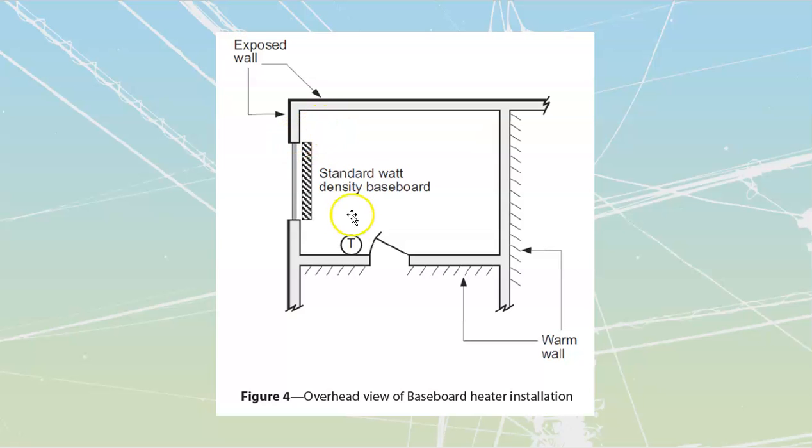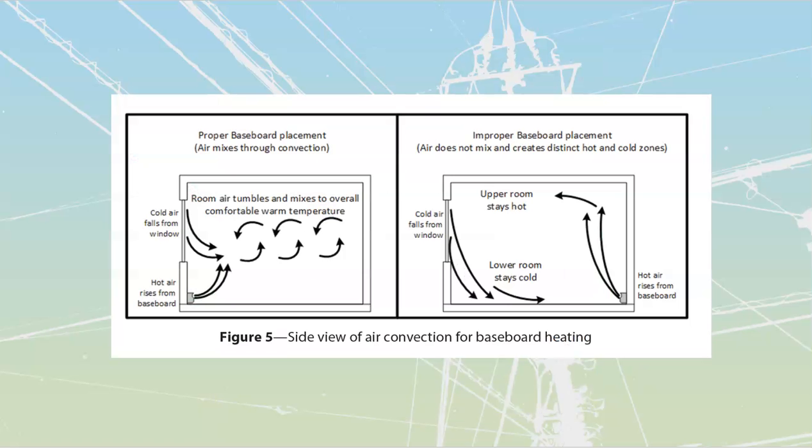But the thermostat you want to have opposite. You don't want it directly over top of any heating ducts or close to any light bulbs or anything that is going to produce a lot of heat, or where you're going to have direct sunlight on it, because obviously all of those are sources of heat that are going to cause erratic operation of it.